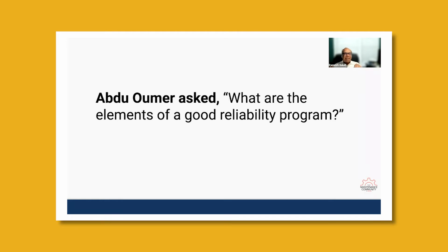Second, have an effective PM program based on FMEA and RCM philosophy. If you have a good maintenance PM program, it means you are catching things during inspection, during the PM, and then you have a corrective maintenance program to correct those findings. Okay, so you're doing those. Again, I can talk for hours on what a good reliability program should be, but in limited time, I think this should be good enough for this question.